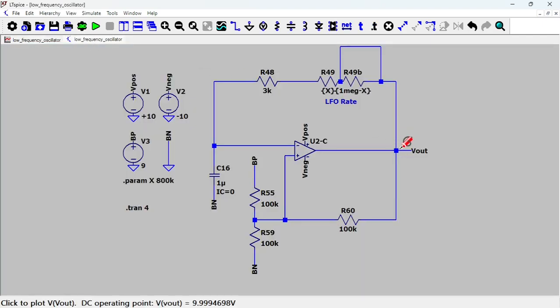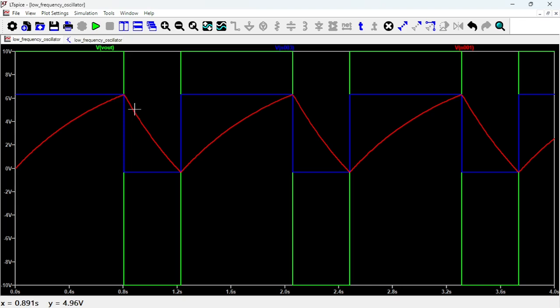So now you don't have plus 10, you have minus 10 volts here at the out. What happens then? For sure the capacitor is going to discharge. It cannot discharge into the op-amp, it has to discharge this way. So that's what you see here. It's discharging, going down this way.